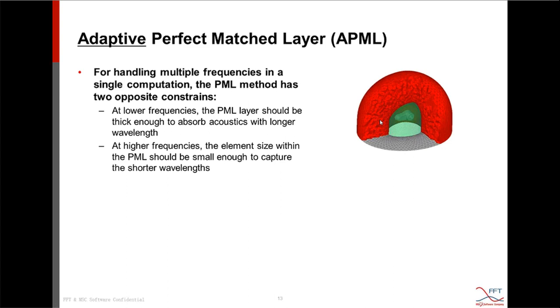While at higher frequencies, the acoustic wavelengths will be shorter, and as we are using a discretization-based method, the individual elements in the PML region will be small. So as we are analyzing problems through a large frequency range, one single PML mesh is not the optimum solution.